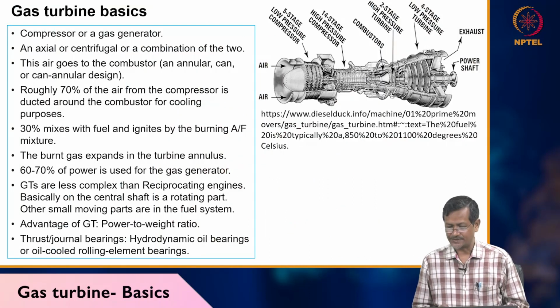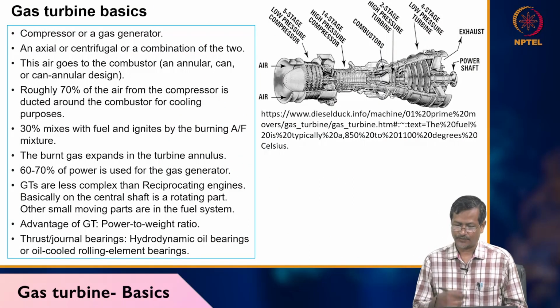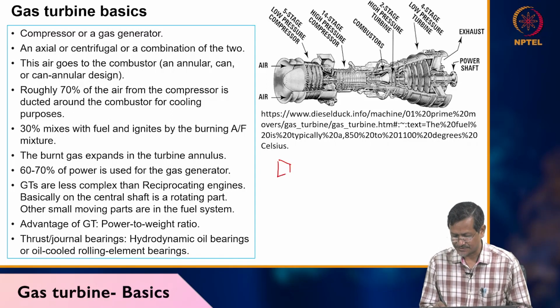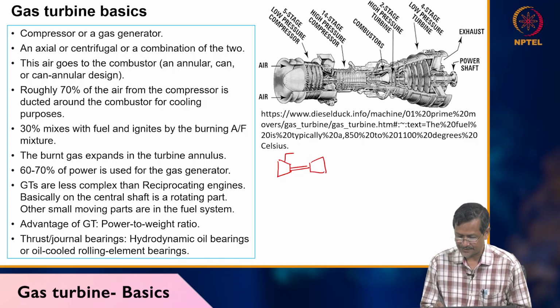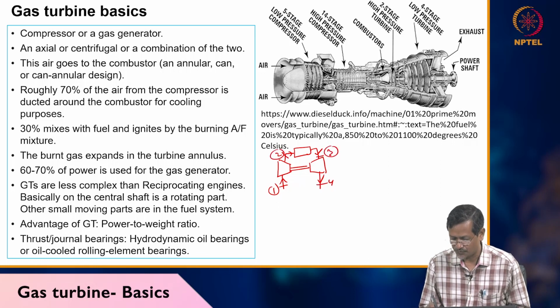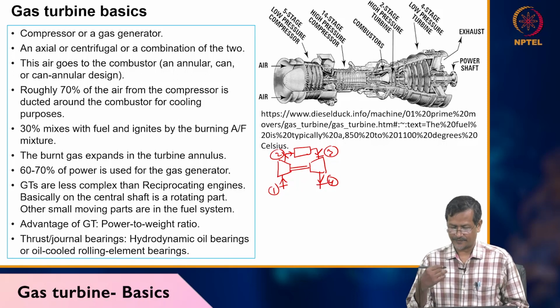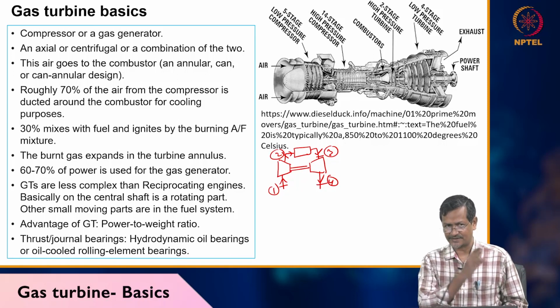You can see the gas turbine engine resembles what I have drawn: compressor, then shaft, then turbine, then one combustion chamber, with entry and exit, 1, 2, 3, 4, the processes. And it is actually an open cycle, because the same gas is not going back to your compressor.